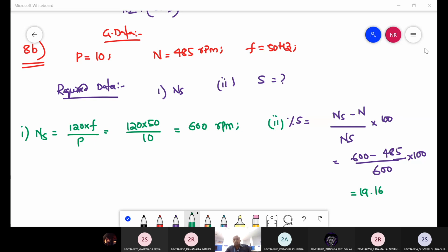In AC circuits, we use I is equal to V by Z, and in place of resistor, impedance. What is impedance? The only thing is, in a DC circuit, the frequency is not a considerable thing. We don't have the frequency, so reactance terms are not there in DC.